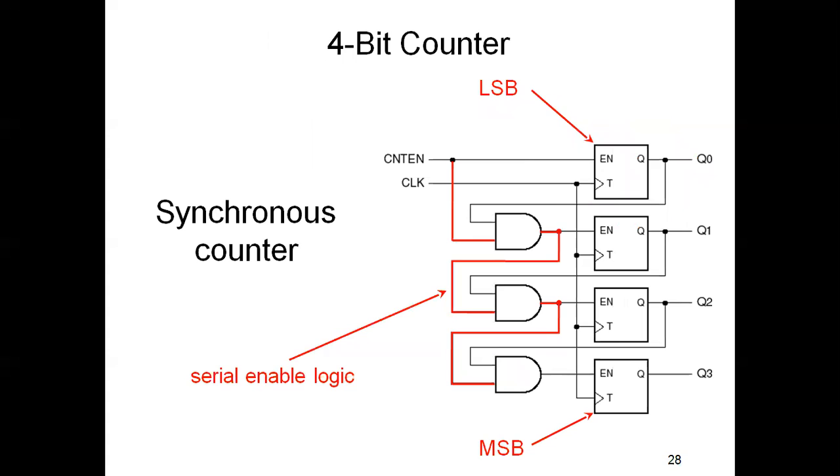A 4-bit synchronous counter, which we can say uses serial enable logic. Here a single clock is applied to all our flip-flops.